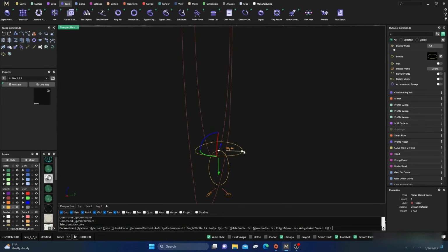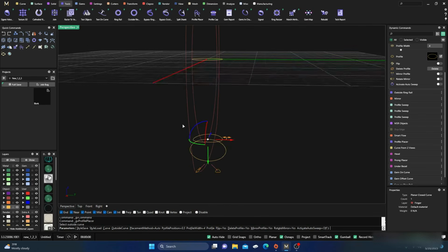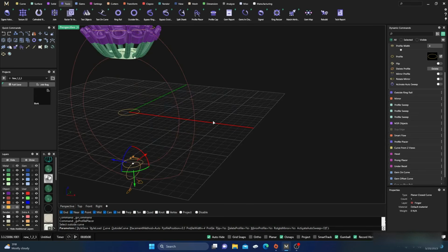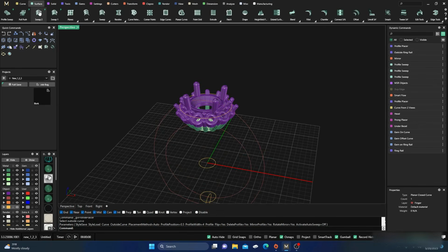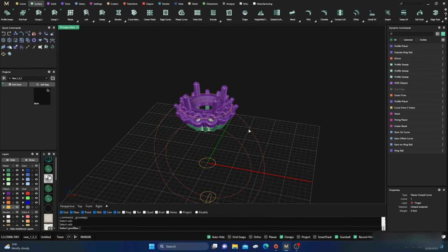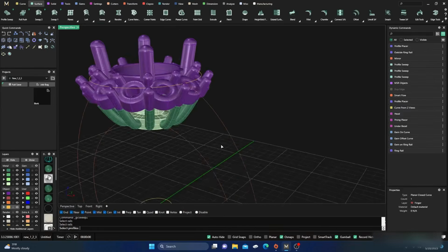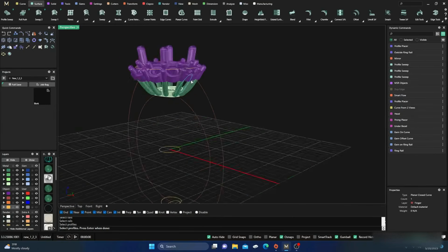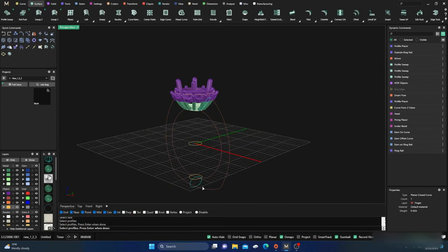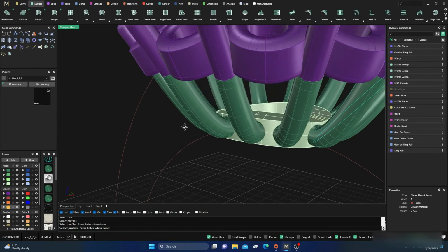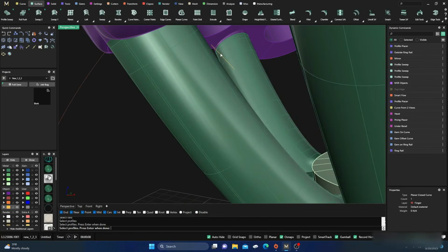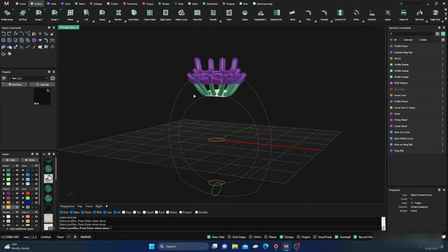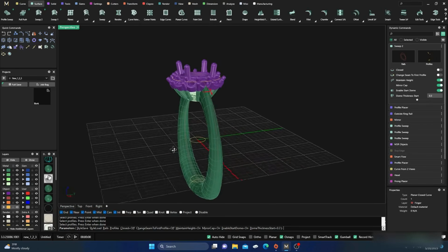And this one we'll do a little manipulation. We'll grab that and we'll make the width, I don't know, around 4. All right, and then from here we'll hit enter, and now we'll do a surface 2 with this ring rail, this profile, and try and get this one over here on the other side. Where is it at? This one here, and we'll hit enter, and there you go.